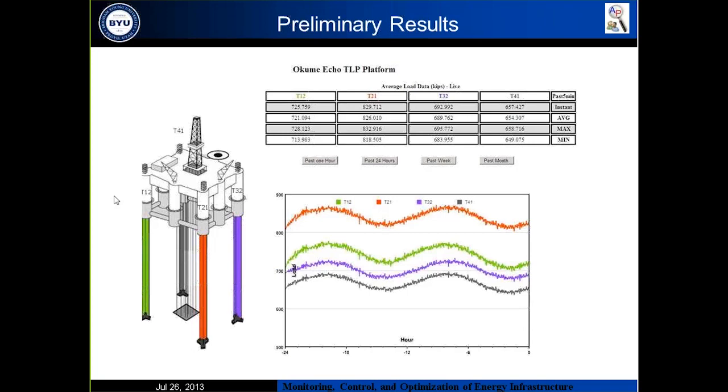The steps I do for calibration is that first I have to change the sensitivity value, because they have their own load cells on the platform. We get the exact values from them, and by looking at the range of the change of load from the load cells, I can find the best sensitivity factors for each sensor.